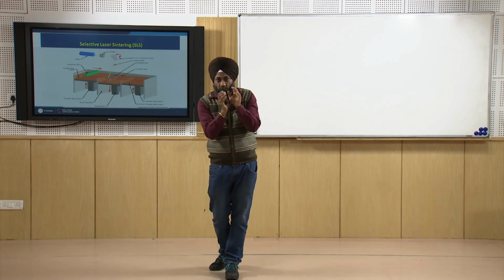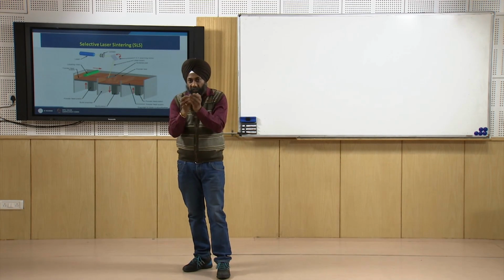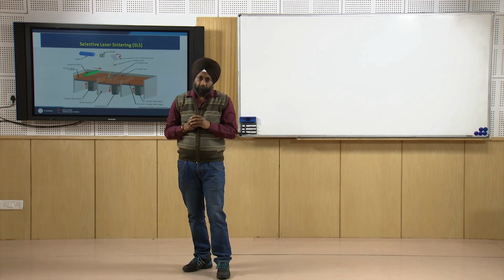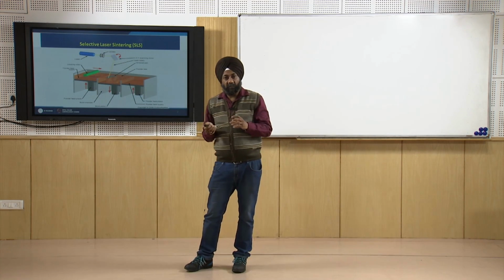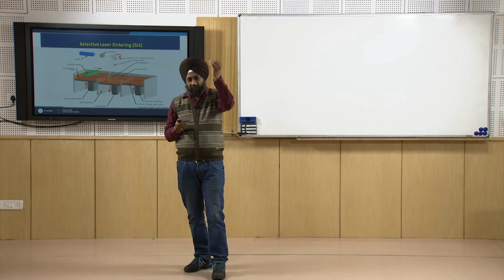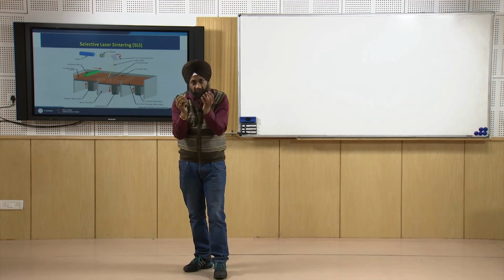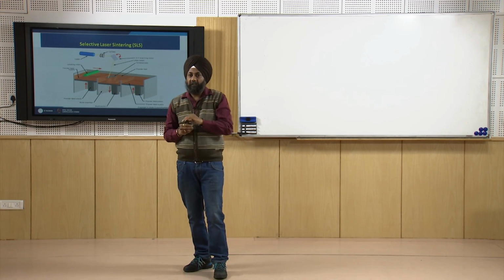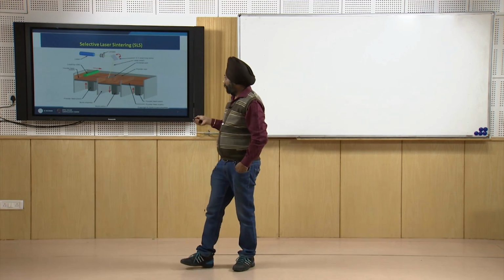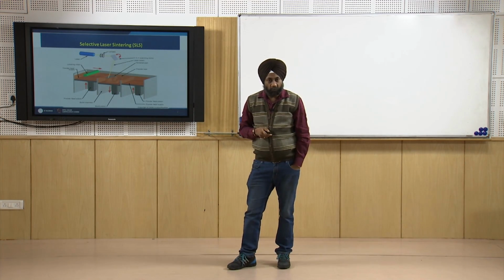We used a photosensitive polymer with a UV laser and converted it into a solid prototype in the stereolithography technique, and in selective laser sintering we took a powder and, using the laser gun, sintered the powder into solid form using the layer by layer technique. So two techniques using different types of inputs, I think, is clear to all of you.